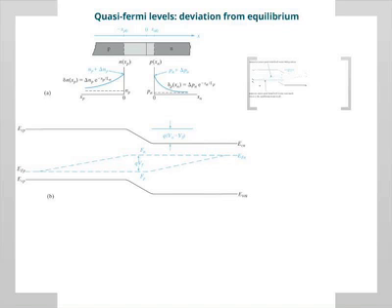So this Fermi level is for both electrons and holes, because it's far away. As you get closer to the junction, they start splitting. Okay? So you get a Fermi level for holes, which is about the same as the original Fermi level because the majority carrier concentration dominates and the concentration of holes really doesn't change very much. You get a few fewer holes because of the recombination. That's a very small number compared to the excess doping that's already there. Okay, so the Fermi level for holes basically remains the same as before.